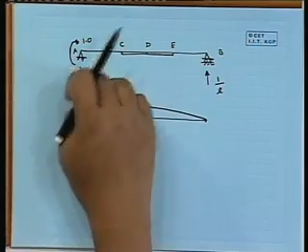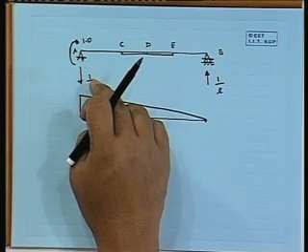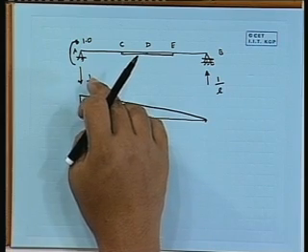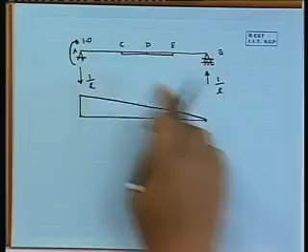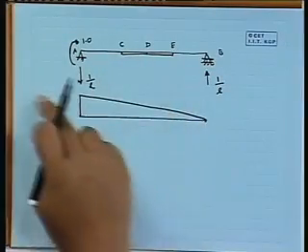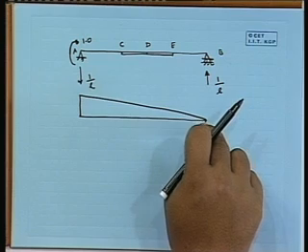It is also a free end, but there is an applied moment. You can just think in this form, there is a cantilever beam with a load. So there is a load, so the shear force will be that force. It is a free end, there is a moment, so the moment will be that applied moment. And inside there is no load, so it will vary in a linear manner and come to 0.